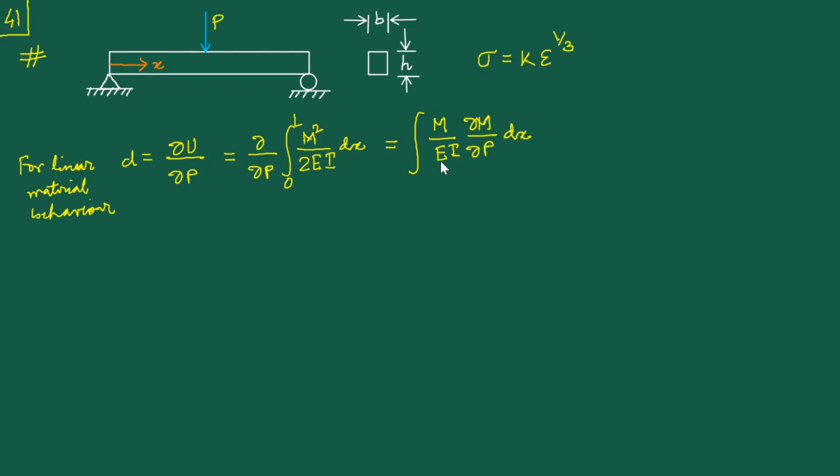So we have been using this formula. Furthermore, as a corollary to Castigliano's theorem, we had also noticed that we could have a corresponding formula for the slope, where theta is equal to del u by del M, where M represents the bending moment.